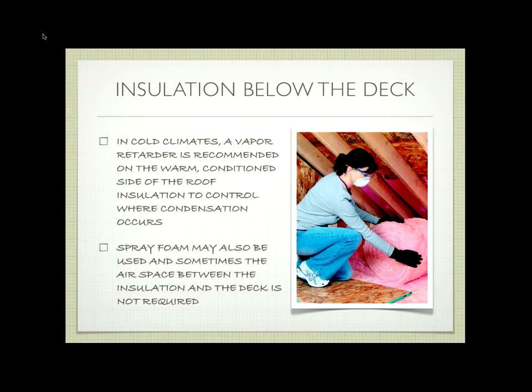So instead, we put that vapor barrier, that vapor retarder, on the warm side of whatever our insulation is. So that barrier is always going to go there. So if the condensation happens, it happens on the inside, on the warm side.